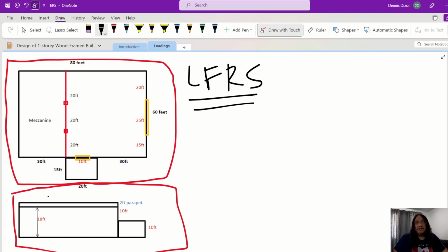But if you have projects like heavy timber construction, then you have posts and beams, and huge curtain walls around your structure, and there's no room for a shear wall. Then another option is cross bracing, or any type of bracing. You can have chevron, inverted, or knee bracing. So you can do something like that.